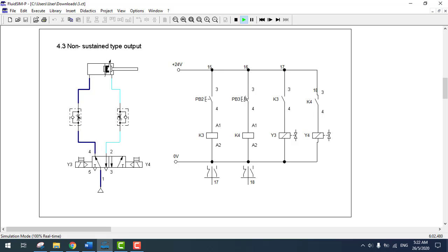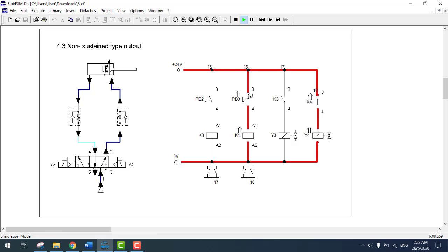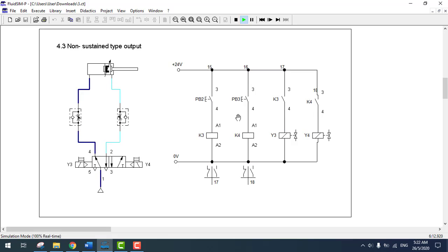The valve solenoid generates an electromagnetic field to shift the spool valve inside the 5-way impulse solenoid valve to the left side. Compressed air supply will fill up the double acting cylinder through the one-way flow control valve, which regulates the flow rate of compressed air to fill up the volume area of the cylinder.